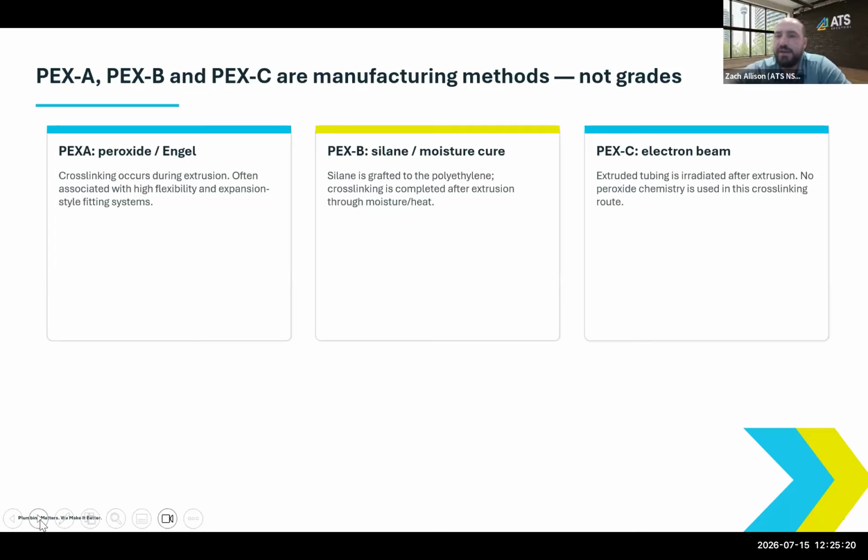They didn't clarify, but I would imagine that it's likely in-floor heating. For any heating application, you have to use an oxygen barrier pipe. They put a coating on the outside of the pipe, and then oxygen won't be able to permeate into the pipe. Because obviously we know in a closed loop heating system, oxygen is the devil. It's going to corrode the boiler, the components, everything in the system.